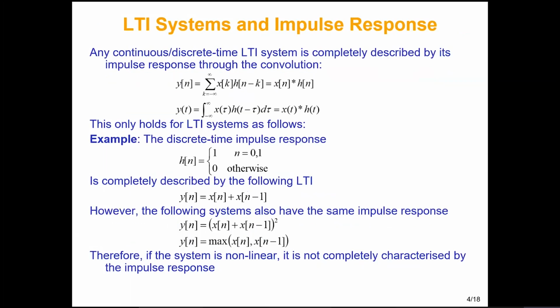And we saw already what convolution is for continuous time, and what it is for discrete time. This is convolution for discrete time, where it means the convolution sum, and we have seen that the order doesn't really matter, but it is basically this summation that you see right here. And for continuous time, convolution means the convolution integral, which is x of tau, h of t minus tau. Again, the order doesn't matter, we can take h of t first or x of t first, it is our choice.